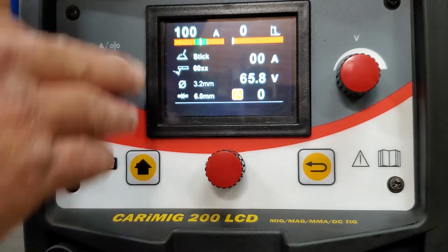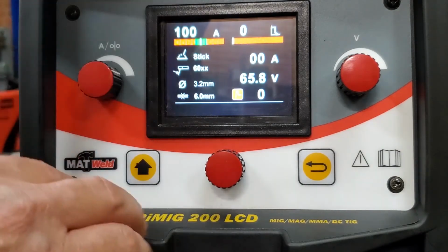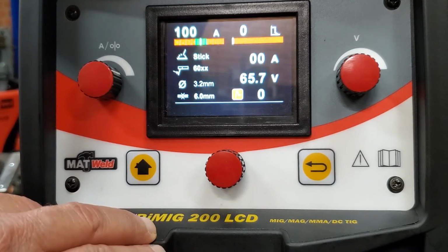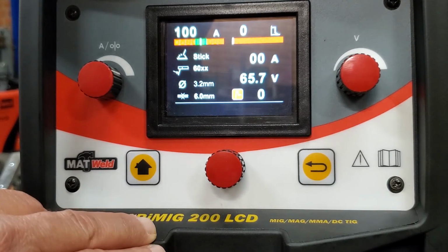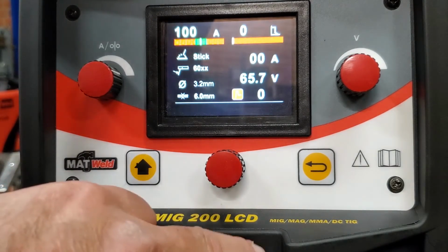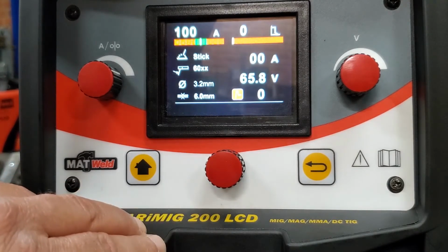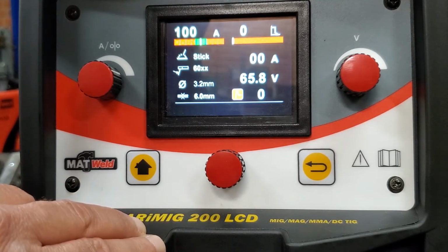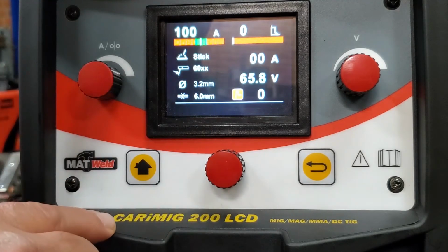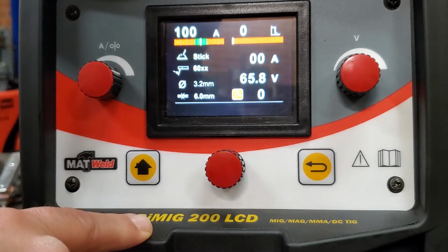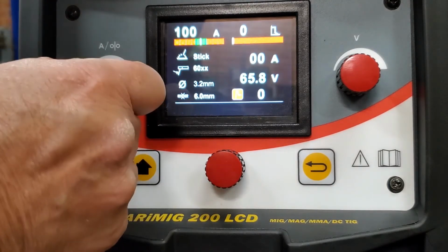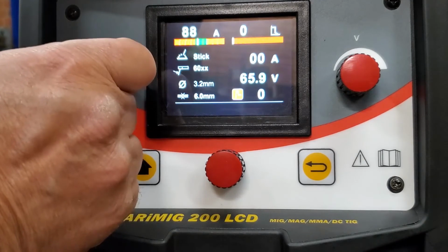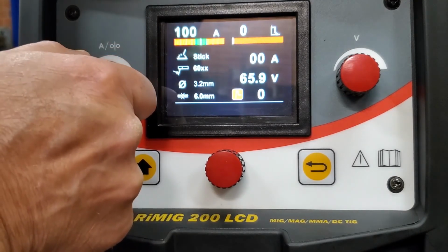100 amps, according to the science of the machine and all the formulas out there in the world, based on what you selected, you need to be at 100 amps. 99.9% of the time, that is the correct amperage. However, we're all different as humans. My speed of welding and your speed of welding might be two different things. My angle of the electrode that I'm holding on the holder, same, and the height of your electrode. Those are all factors which obviously can't be accounted for in the science, but you can adjust within the green parameter that you will see.